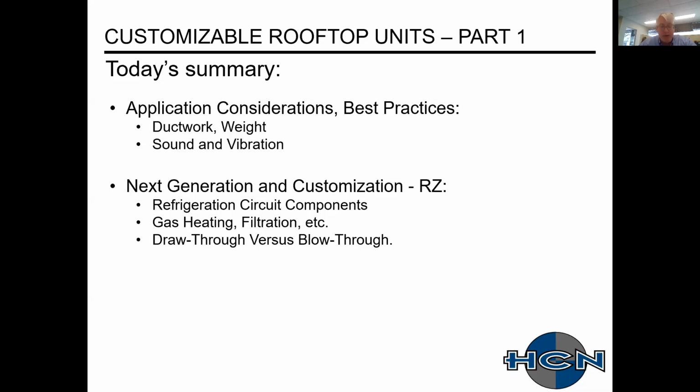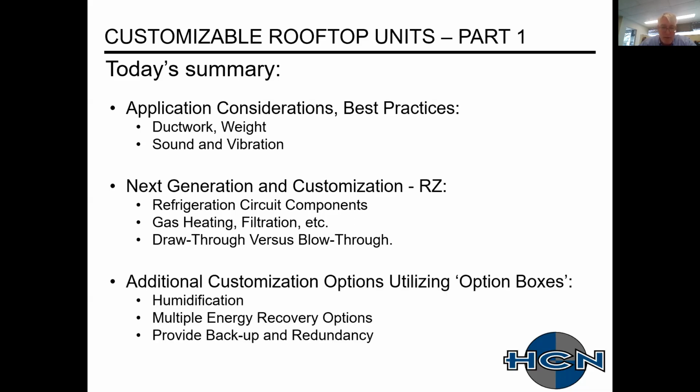Gas heating filtration, once again, is following the same path as the other devices, just more options, better components. Draw-through versus blow-through configuration. And then lastly, we went through the custom option boxes with humidification that was available, the different energy recovery options, as well as the ability to provide backup and redundancy.